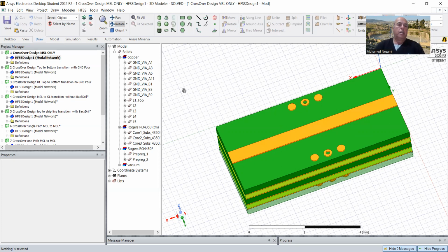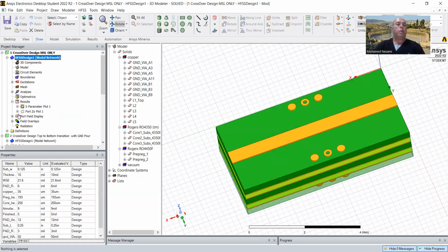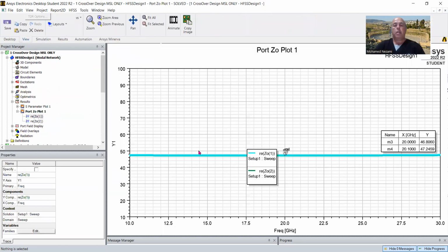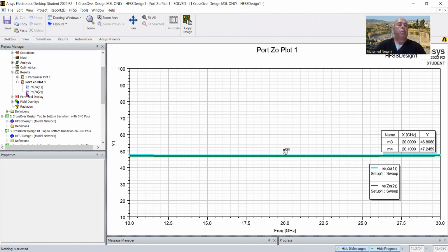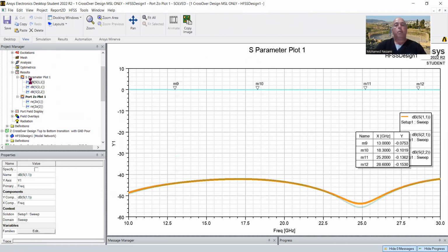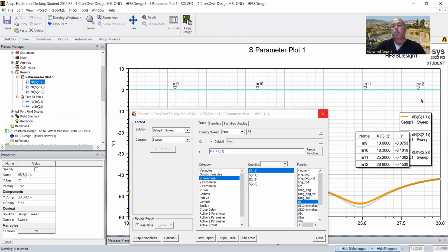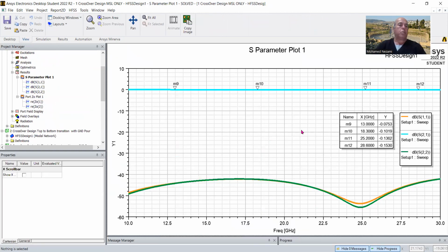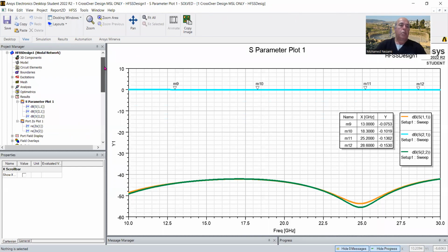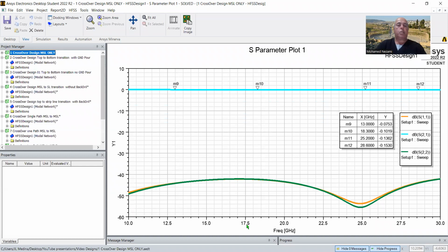And then here's the line, and you can sweep and see basically the impedance of this line is 50 ohm. So that is here, 47, 46-ish. We can fix that later, but that's good enough for this application. And then if you look at the insertion loss, this is the insertion loss, and it does match the theory. If you go to the line and you find the return loss is good, so that shows that it's a good 50 ohm.